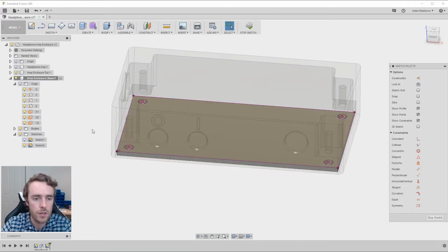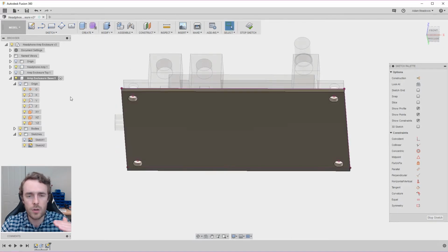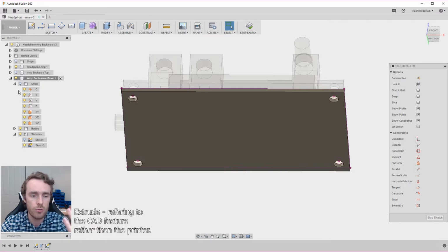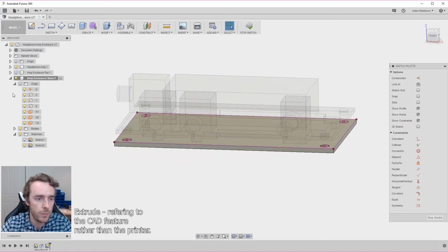Excellent. So now let's get the solder points. So when we're extruding upwards to the PCB, we want to make sure we're avoiding those solder points. That line that we put on the first sketch in our reference geometry is going to outline those, so we don't accidentally extrude plastic up into those points. So obviously we need that geometry. Let's hide this body.